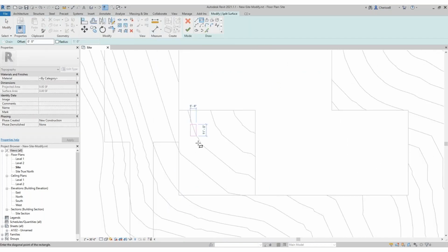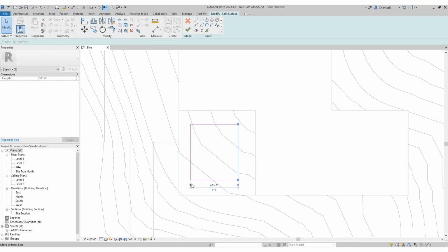Next is the pool. Now I don't give any indication on how to get all sides 20 feet, but here I'm utilizing the temporary dimensions, which I've also seen people use reference planes to map this out, or they dimension it and then select the line and modify its location. I think this would be a great way to show people different ways of getting that in there.